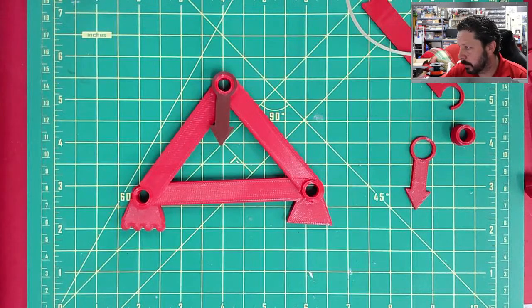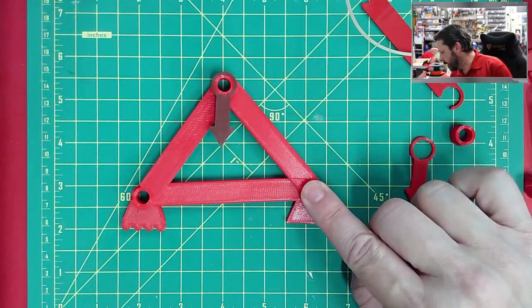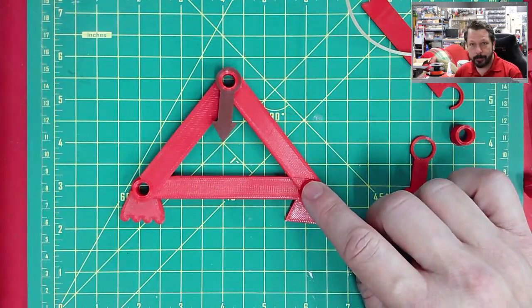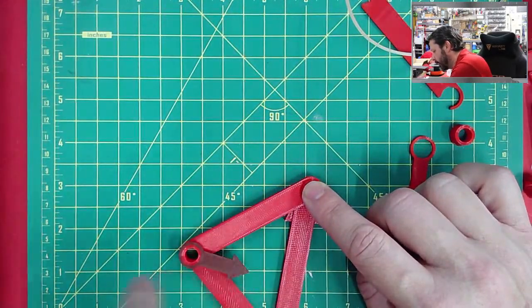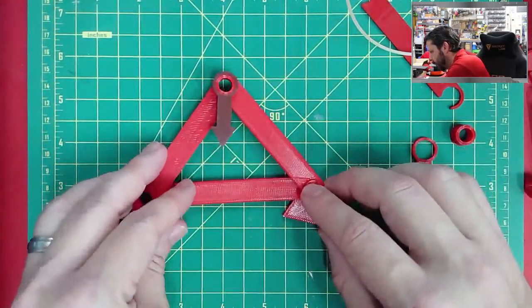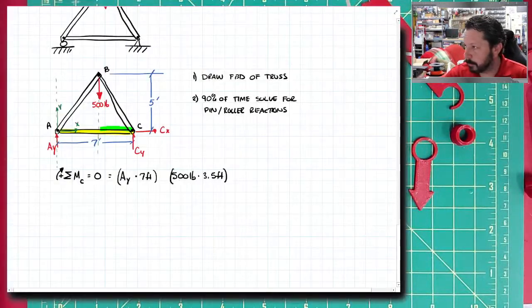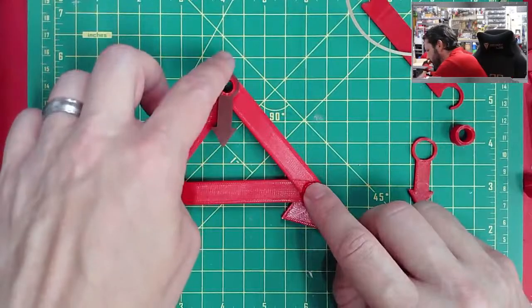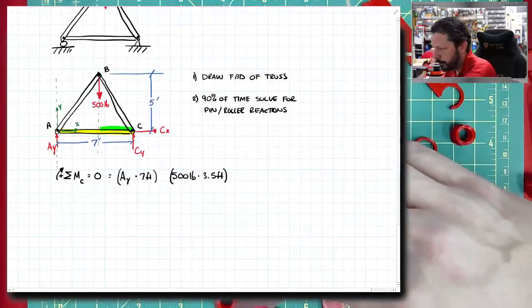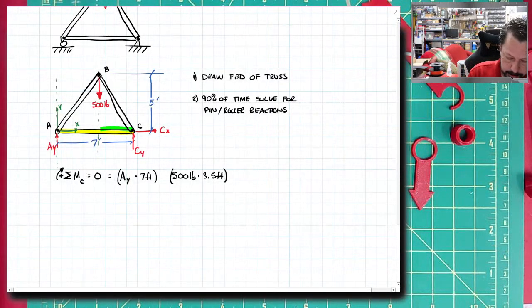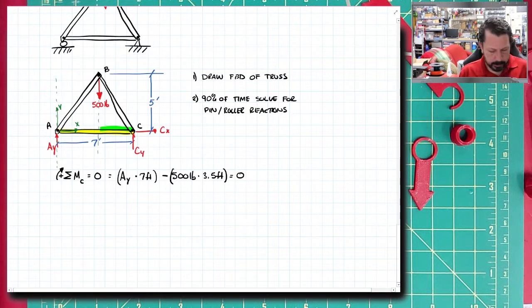And this force, our equation is assuming that we're pinned at C, and we push down, it would make the body rotate counterclockwise about point C. So pushing down where this force was applied goes counterclockwise. And I said that clockwise is positive, so counterclockwise has to be negative. And those are the only forces that create moments about C. So they equal 0, and I can solve for AY.